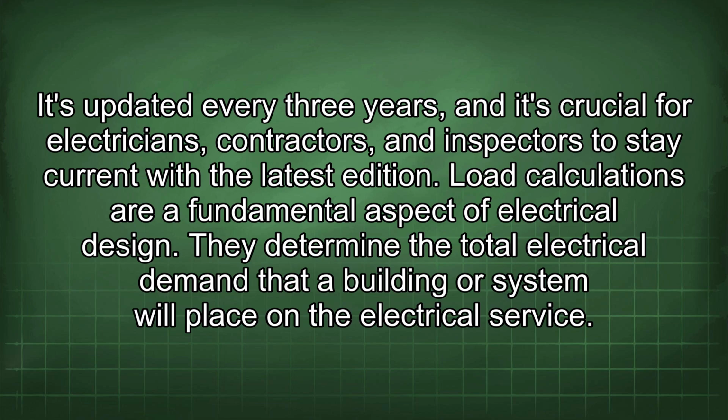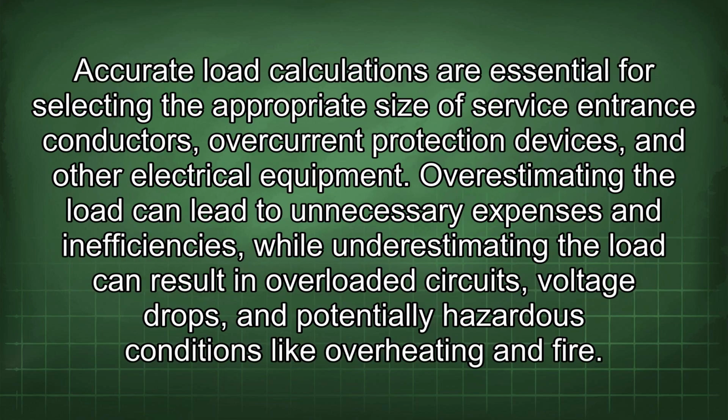Load calculations are a fundamental aspect of electrical design. They determine the total electrical demand that a building or system will place on the electrical service. Accurate load calculations are essential for selecting the appropriate size of service entrance conductors, overcurrent protection devices, and other electrical equipment. Overestimating the load can lead to unnecessary expenses and inefficiencies, while underestimating the load can result in overloaded circuits, voltage drops, and potentially hazardous conditions like overheating and fire.